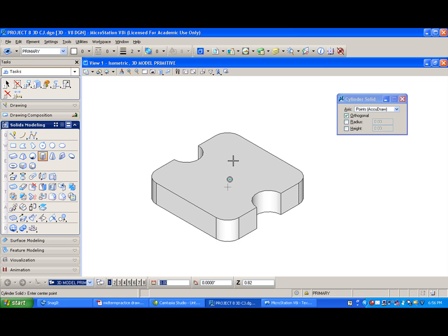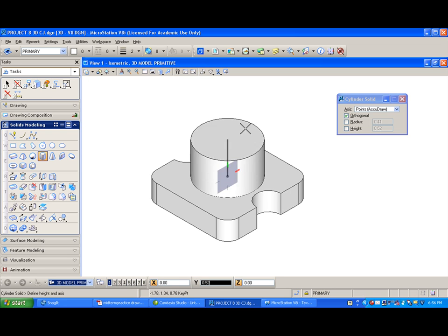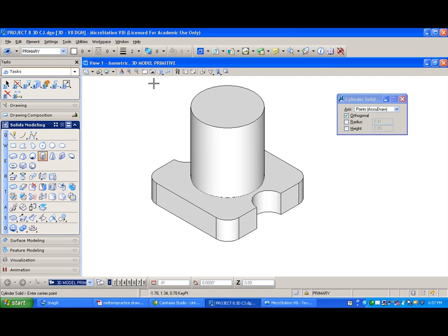Yeah, that's not, well, I'm going to hit my tentative, hit O, hit enter, and just find that center point. So now, just using the enter and solid, it puts me up on the top of this object. And again, 0.41 is the radius, and we pull the height up. The height on this is 0.95 inches. 0.95, left click. So now we're looking at rotating this.